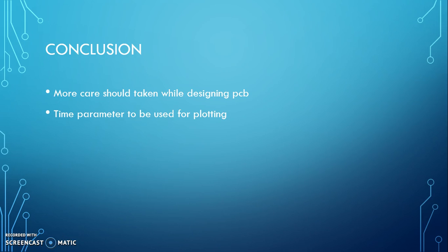But to conclude my presentation, I will share some of the experience I gathered from my mistakes. I should have been more careful and cautious while designing my PCB. In some places, I designed footprints for 0805 size components, but later I found that the only available and cheap components are of 0603 size. It created a lot of problems for me. I had to solder some traces manually to connect some of the components. Maybe because of that, my project failed to monitor continuously for more than a few breathing cycles.